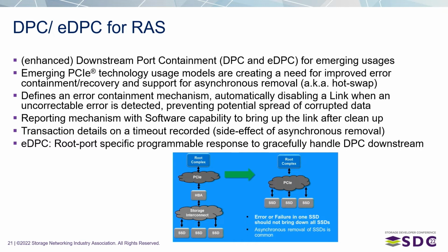hey, as you move from this HBA kind of topology to a direct PCI Express connect, people always plug out the wrong SSD, and you need to make sure that you're not bringing down the whole system. So we defined the containment such that the containment is limited to the device that is being impacted. All the other devices will continue as usual, even though they're under a switch hierarchy. So if you're under a switch, you don't want the CPU's root port to be timing out on the other SSDs that are not really impacted. Those are the types of things that PCI Express did to address those issues.